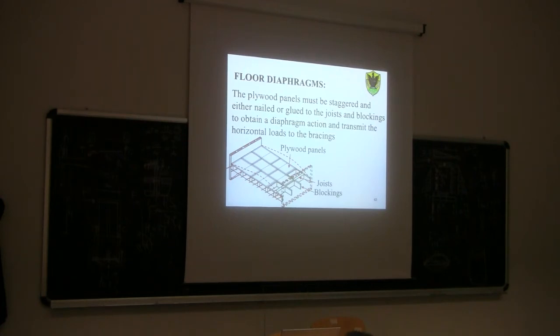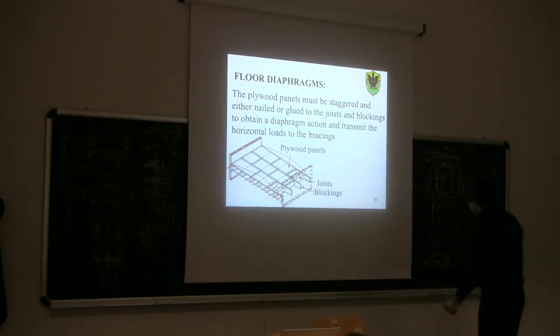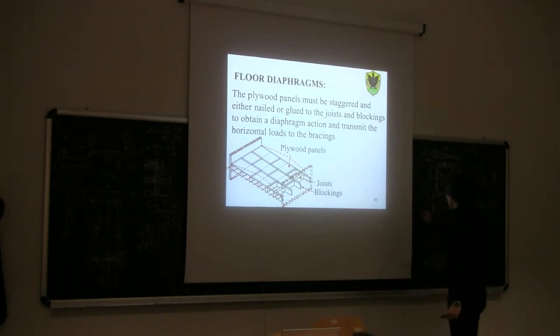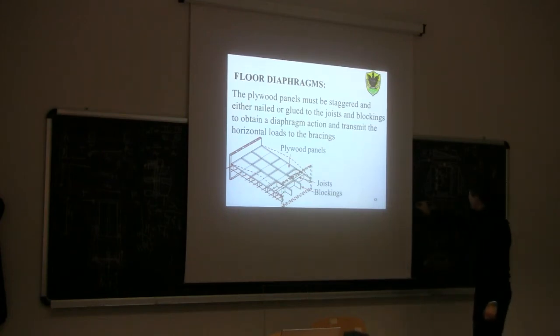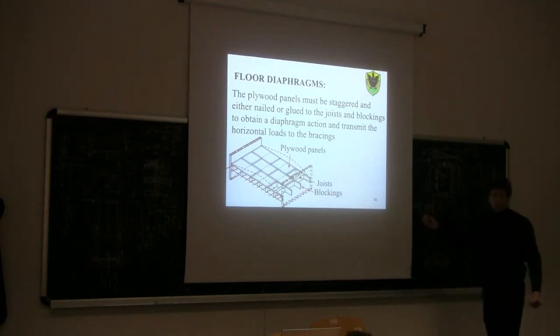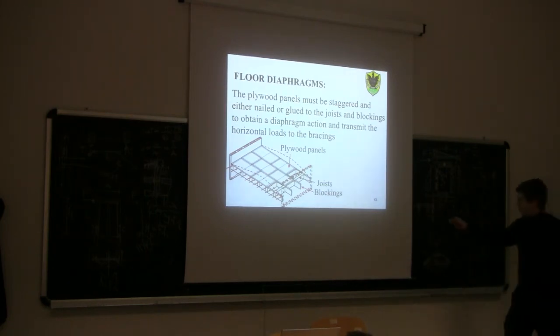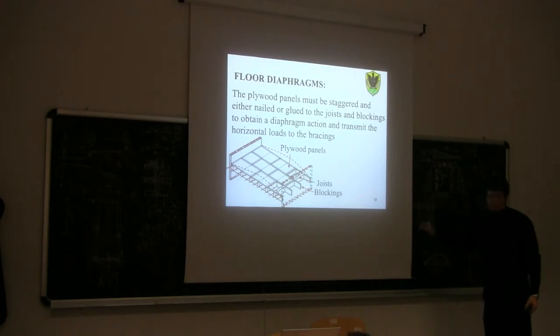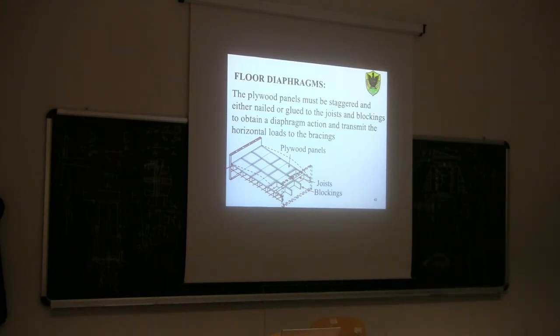I mean, they may be loaded if we consider a kind of composite structure. So, for example, here we have one joist, here we have one sheathing. So this could be considered as a composite structure, where we have the top sheathing, kind of a T section. So in this case, they would be loaded if you consider this as a composite structure. But if we ignore this composite action between the two, what do you think, are those nails much stressed under the vertical loads?